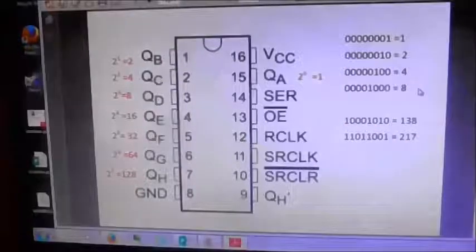And what the data sequencer does is it sends it through 1 bit at a time. Now, you can send through most significant bit first or least significant bit first. And I usually find that it's easier to send through most significant bit first. Least significant bit first means it appears at the output as it was at the input. The most significant bit first means it's inverted, and I usually find it easier to work with the inverse.